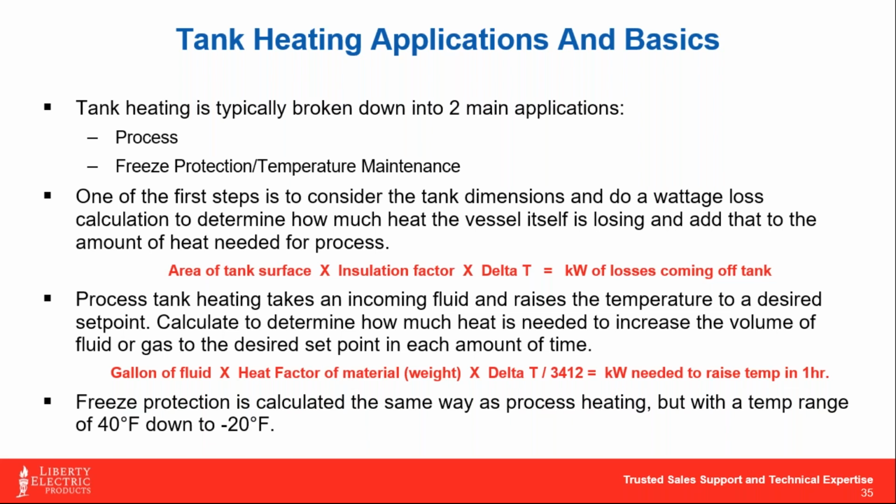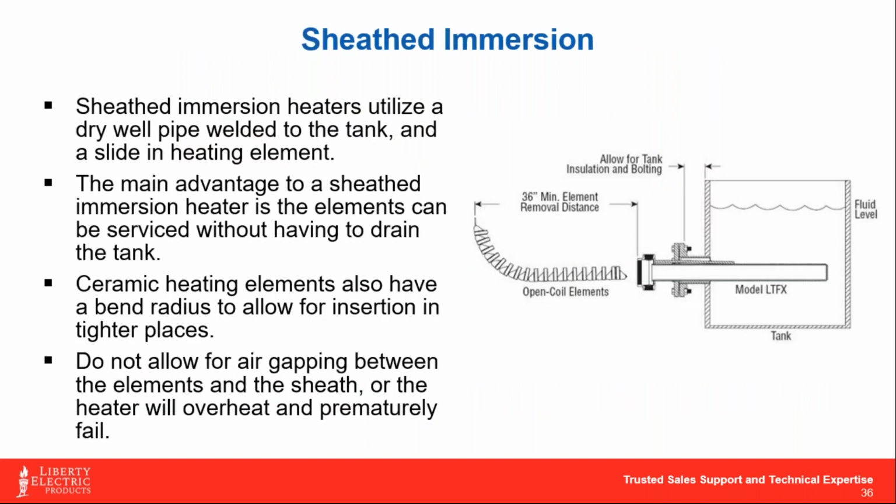Okay, so again, if I use a 100 kW application and I want it done in a half hour, it's going to take me 200 kW to do that. Okay, if I want it done in 15 minutes, it's going to be 400 kW, and so on and so forth. If I want it at 7 minutes, it's 800 kW. So you can just kind of do the math in your head going the other way as well, that if you're willing to give the process a little bit of time, we can get away with a smaller heater.